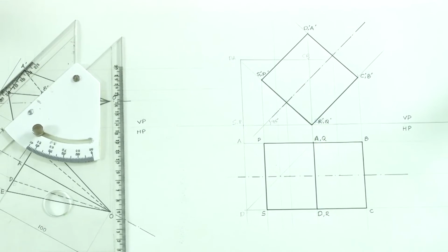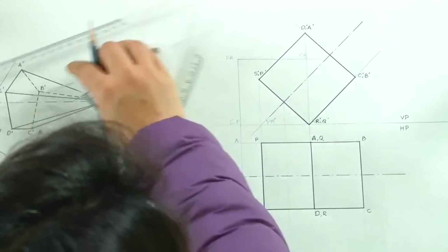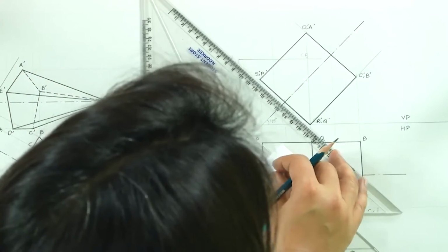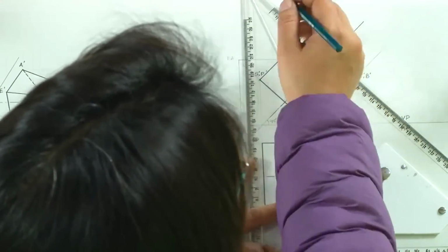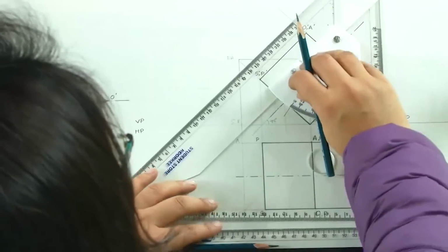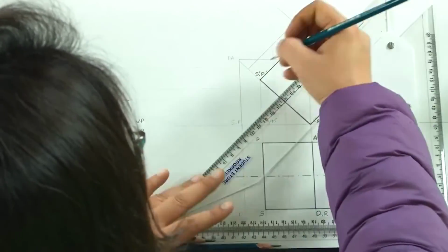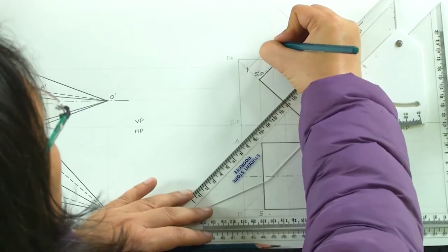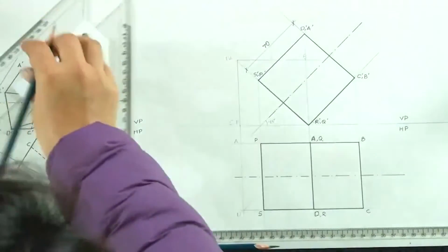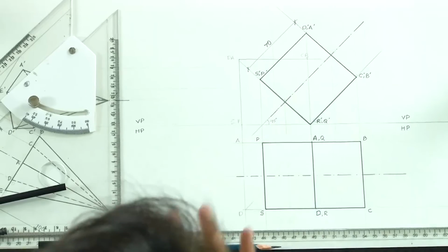And since it is singly inclined, we will still be seeing the true shapes. And where will we see the true shape of this true side dimensions? In front elevation, because the axis remains parallel to VP. So what we have here is the true sides of the cube. So we said that the cube is 70 mm side each.